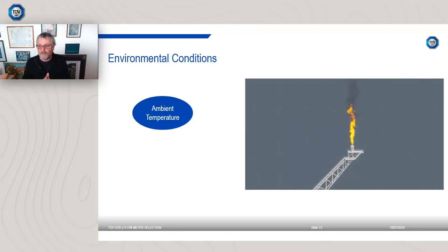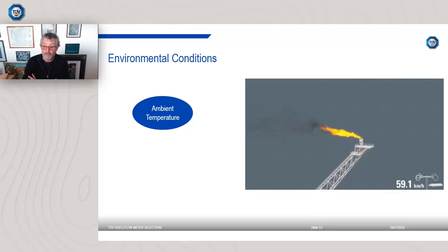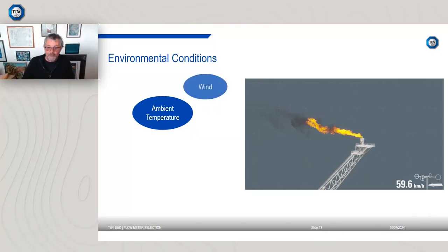You know, is this an LNG terminal in the Arctic Circle in Norway where everything could freeze up or ice up? Or is the equipment going to be installed very close to a flare line, which, if the flaring is happening, will bring the ambient temperature extremely high? I've actually been involved in work where occasionally the ambient temperature at the equipment got very close to or over the 55 degrees C rating for the equipment being used. That was never considered during the selection process.